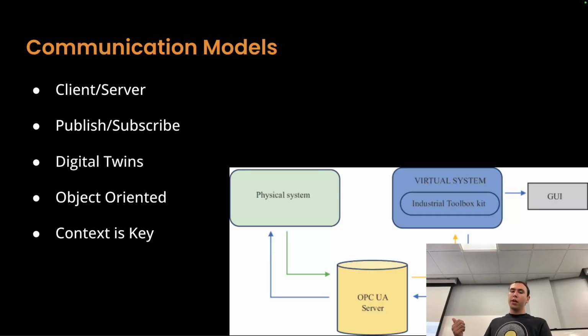And this protocol, along with security, also wanted to make sure that context is very important. So say you have your PLC and you're reading from its value and it's 58. And then you send that value 58 up to your SCADA system, and it's a different engineer, and he's having to configure the SCADA, and he reads this value 58. And he's like, okay, where's this coming from again? It's just 58. Is this time since a thing has occurred? Is it temperature? Is it whatever, right? So in OPC UA, they defined a way to actually share the data with a whole lot of context. So in addition to labeling it, giving it an actual name, the data type, if it's a float, a Boolean, whatever. So yeah, that's essentially the communication model for that.